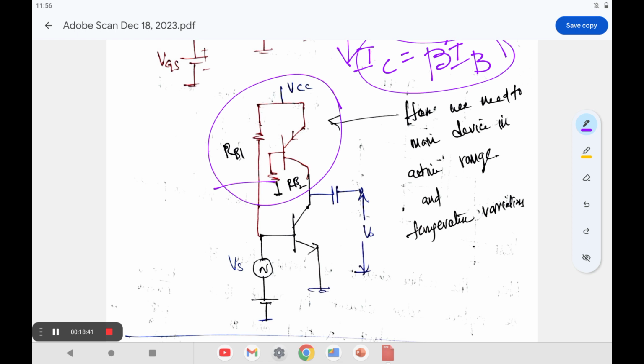I think all of you have some basic idea. In the case of the BJT, the minority charge carriers increase with the reverse bias due to temperature. Every 10 degrees centigrade, it also doubles. We already studied these points in our previous curriculum. The BJT is very temperature sensitive in some applications.